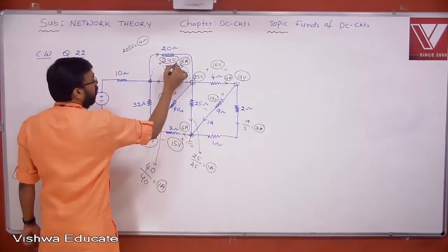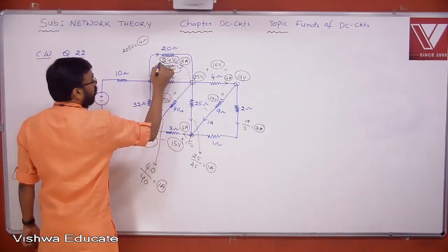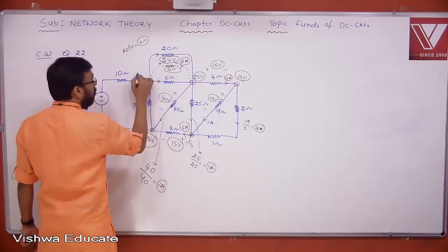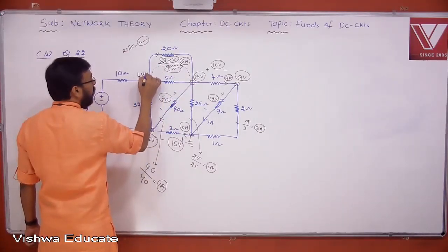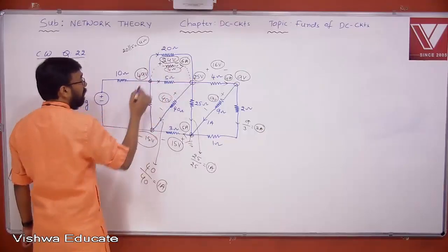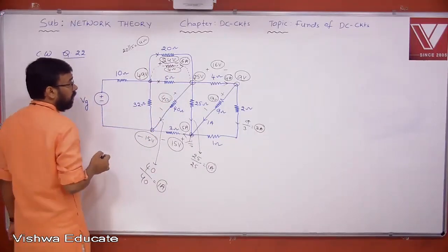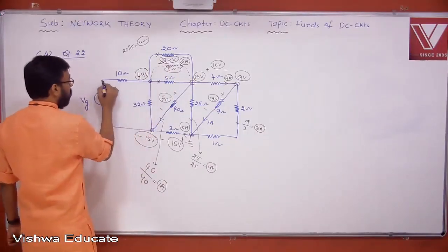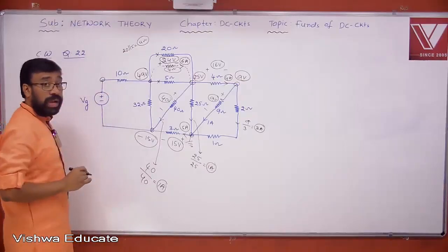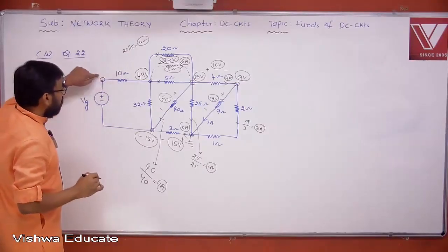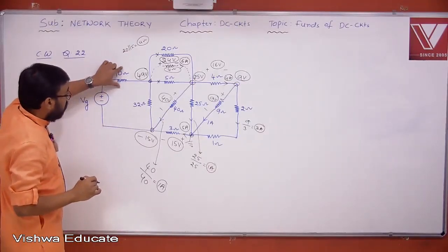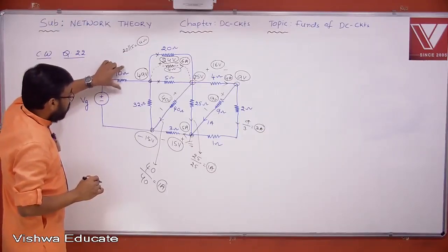You are jumping from lower potential to what? Lower potential to higher potential. Take the voltage. This is going to be 49 volts. You take the voltage 25 plus 24, 49. Now jump from this point to this point. To jump from this point to this point, you require the voltage across it. And to find the voltage, again current.